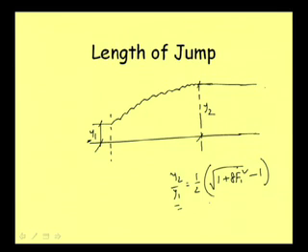So, because of this we may have some computational error. In reality there will be some frictional resistance acting on the boundary side, or there may be some form loss also. These losses will influence the value of y2, but still now you have some idea of where the y2 will be, and then you observe carefully.